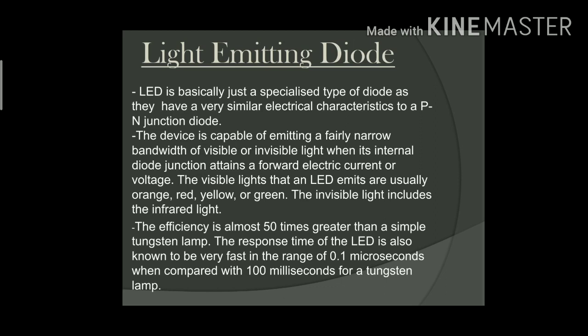Third point, the efficiency is almost 50 times greater than a simple tungsten lamp. The response time of the LED is also known to be very fast, in the range of 0.1 microsecond when compared with 100 millisecond for a tungsten lamp.